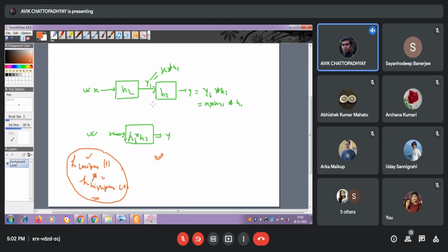Always remember, whenever you design and implement, the fewer active components you use, the safer you are, because active components are a powerful, potential source of noise. The more you reduce their number, the more you rule out the possibilities of noise. Noise is a very dangerous thing.